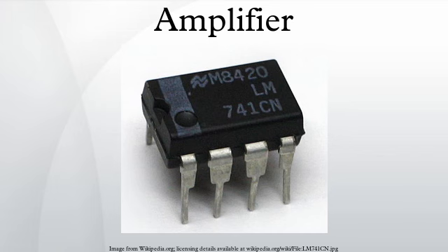The efficiency of previous AM transmitter designs was proportional to modulation but, with average modulation typically around 20%, transmitters were limited to less than 50% efficiency. In Doherty's design, even with zero modulation, a transmitter could achieve at least 60% efficiency. As a successor to Western Electric for broadcast transmitters, the Doherty concept was considerably refined by Continental Electronics Manufacturing Company of Dallas, TX. Perhaps the ultimate refinement was the screen grid modulation scheme invented by Joseph B. Sainton.